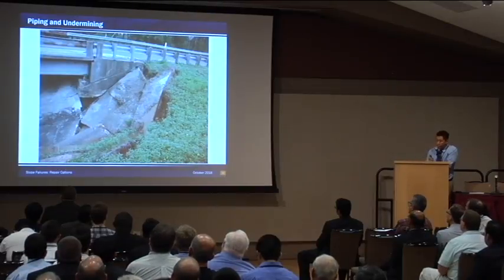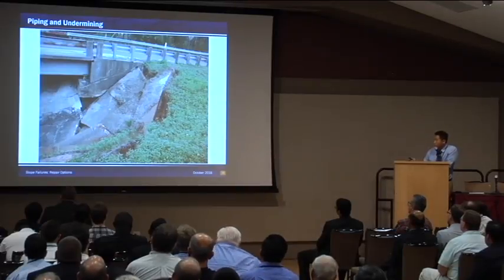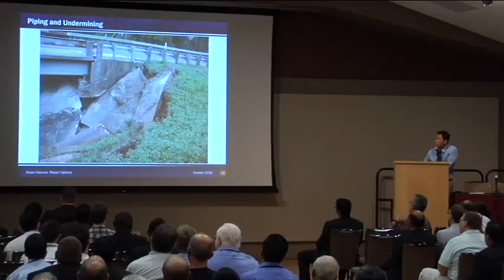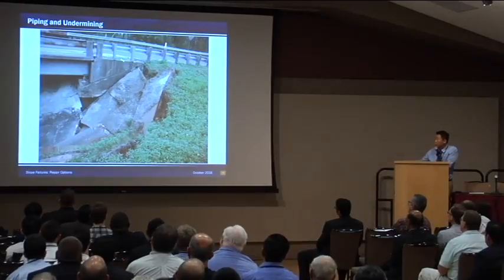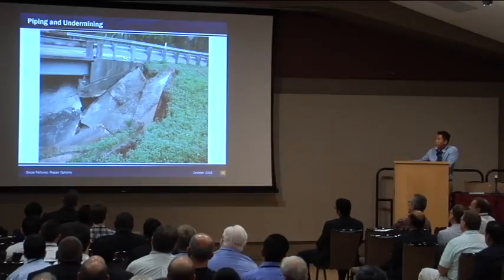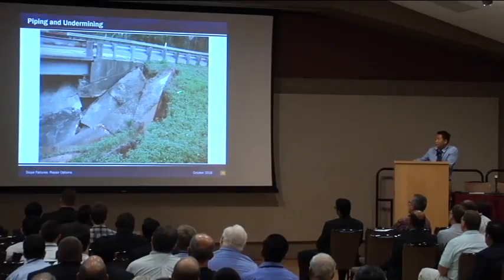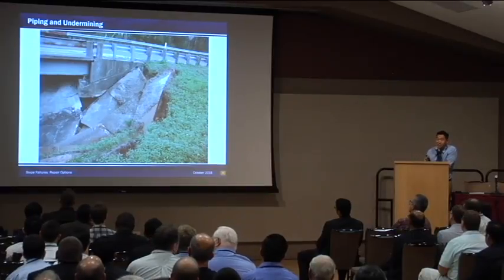This is also a typical undermining and piping failure. The structure collapsed, so remove the structure, place cement to stabilize the sand, and rebuild the structure. And I would recommend putting a concrete curb around here to divert the water. You may also consider putting a shoulder drain down, and maybe a dissipator or storm protection at the exit of the shoulder drain.